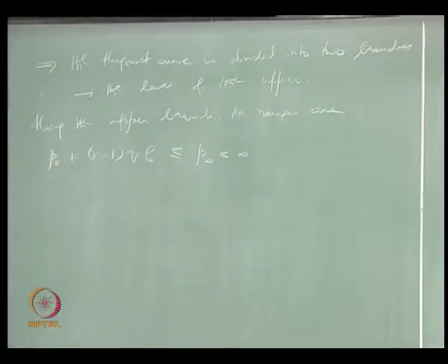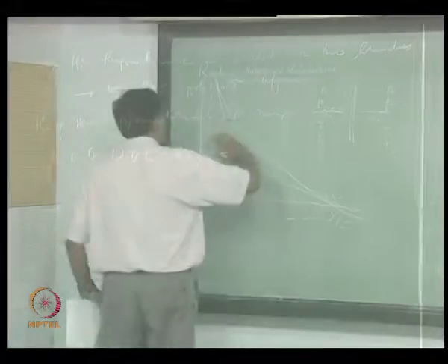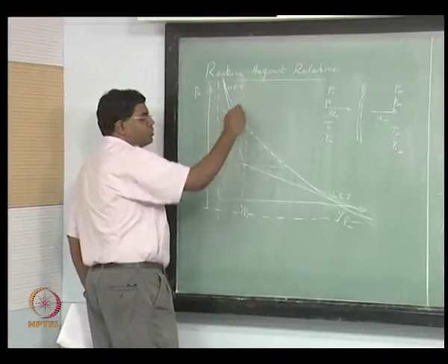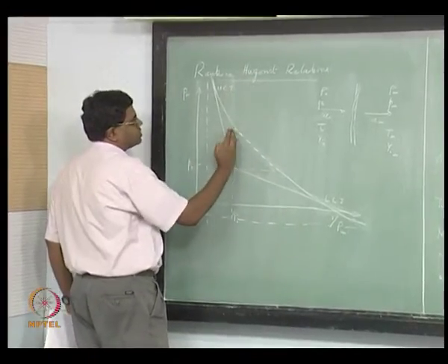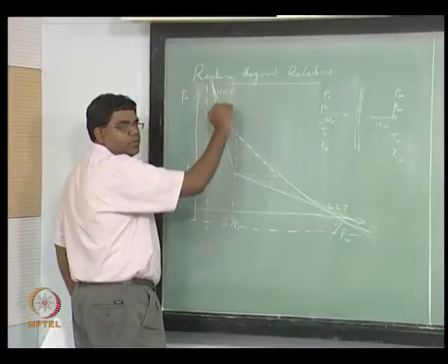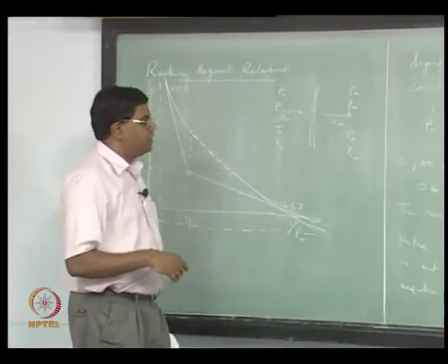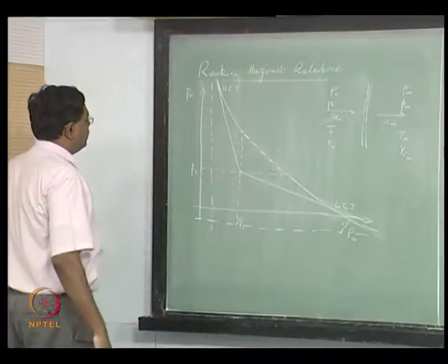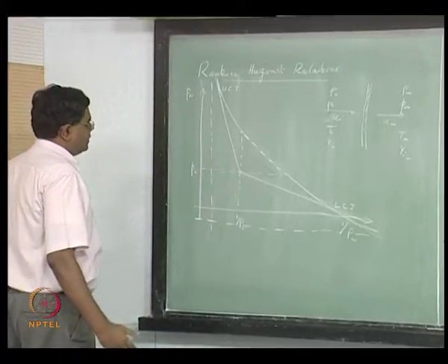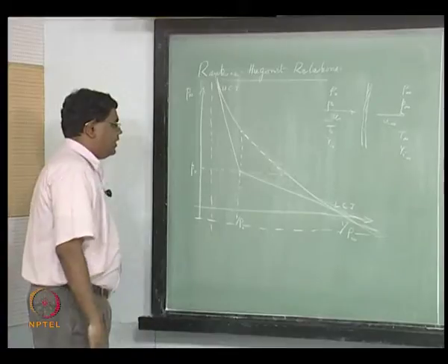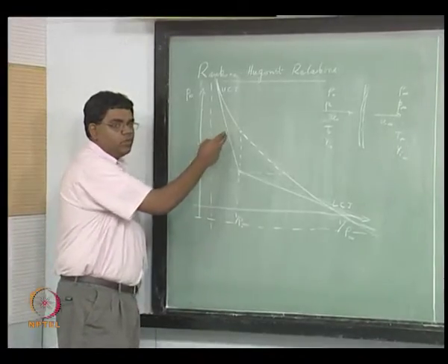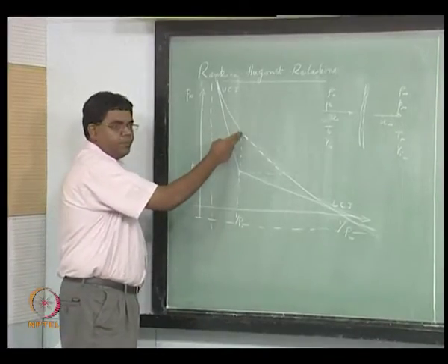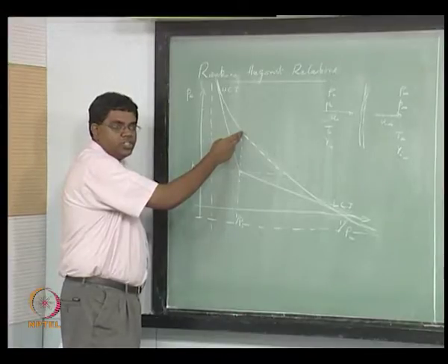So as Q increases, this curve is going to go up. So the point where this intersection happens is going to go up, right. So the lowest value of P infinity will keep moving up as Q increases. So this can obviously be obtained by plugging 1 over rho infinity equal to 1 over rho naught in your Rankine-Hugoniot relation, right.